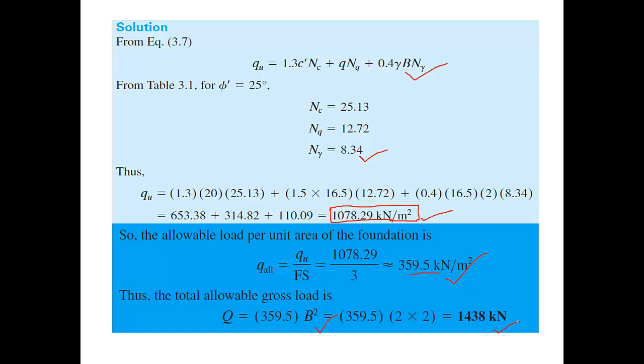But in RCC you do it in a little bit different way, though the concept is similar. In RCC, you calculate the load on the column and you check the dimension of the foundation. Usually you have the column load, and you design the foundation dimension.